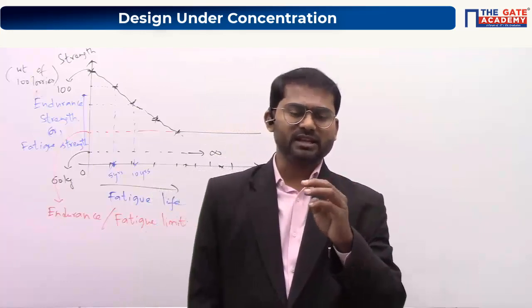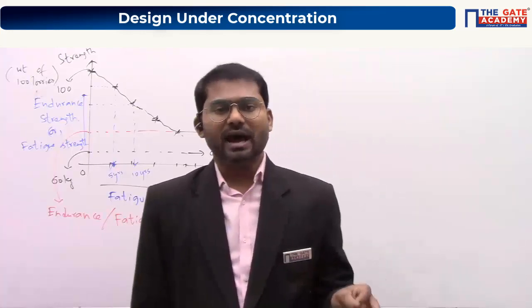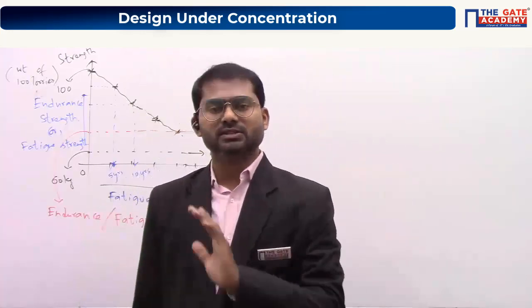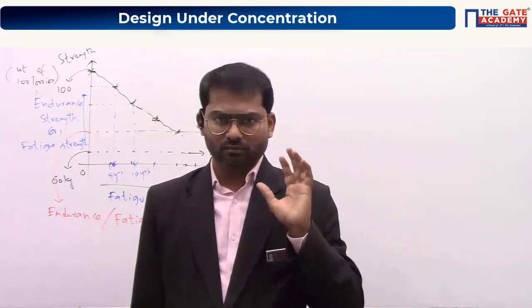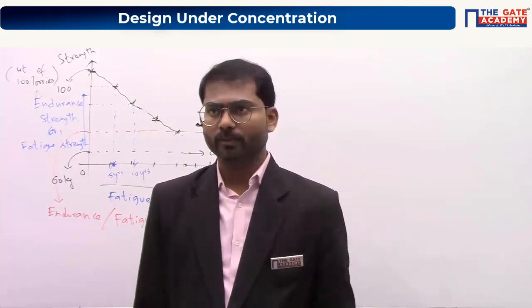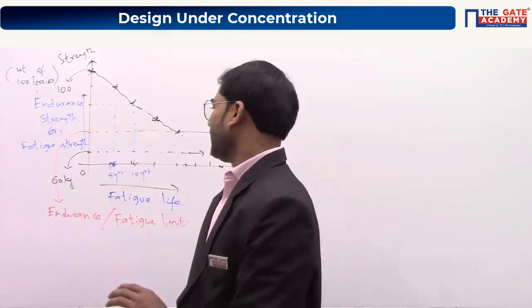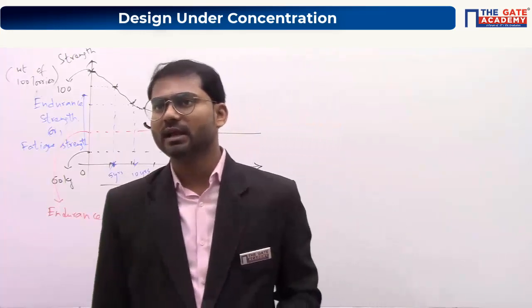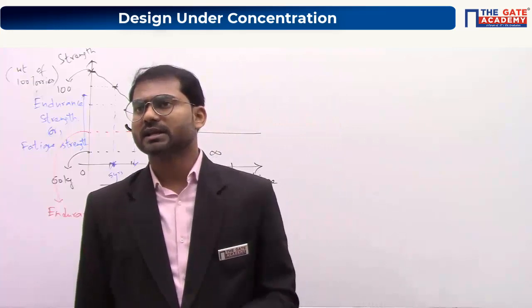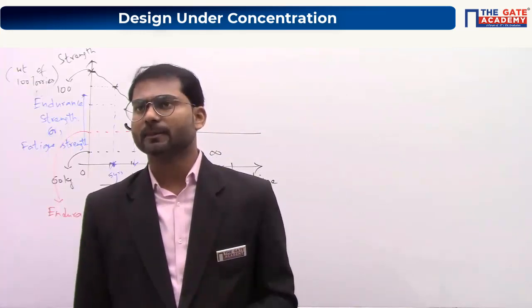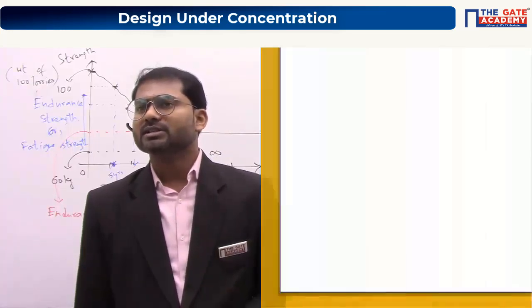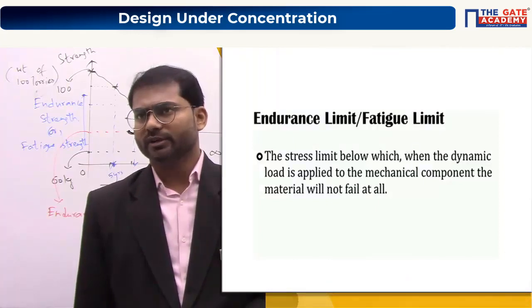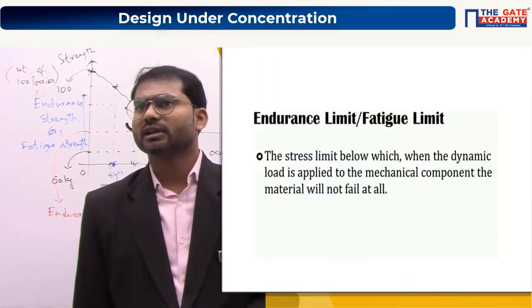If you take the strength of the material, yield stress, ultimate stress, all these are stresses only. There is nothing having units of load. This endurance limit also has the units of stress itself. Endurance strength also has units of stress, Newton per meter square, not newtons here. Understand? Endurance limit is greater than the load to be encountered. Kumar Vishesh, is it clear now?